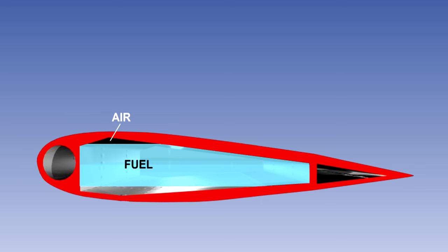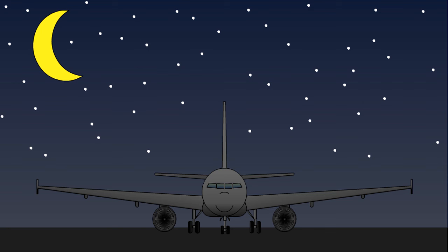Once the fuel is in the aircraft tanks, the main source of water contamination is the atmosphere that remains within the tank. If the tanks are topped up to full, then the atmosphere is excluded together with the moisture it contains, thus minimizing the likelihood that fuel will be contaminated. Caution is required here.